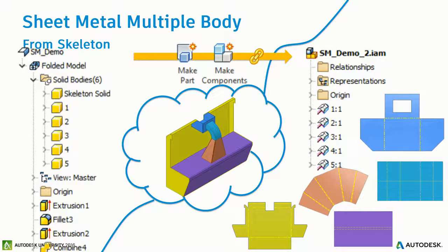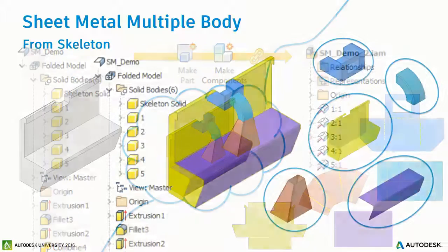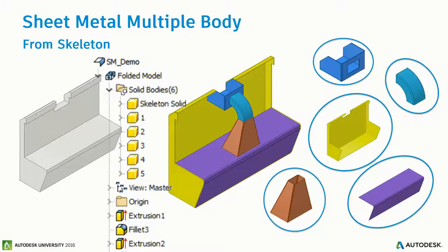You can import solids from SolidWorks or other programs? Yes, directly. Oh, I missed these tips. When you want to import a sheet metal design from SolidWorks or other competitors, Inventor cannot recognize it as a sheet metal part directly. There's one quick way to review it: we can import it in and use the second tool to quickly review it, and use bend, which I demoed a little bit.